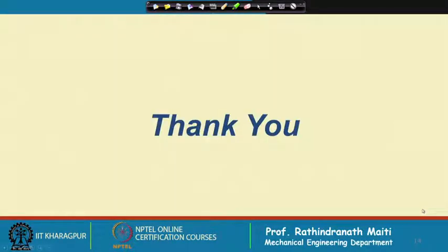Okay. Also the gear data we have provided here, and this is the end of the detailed drawing. Thank you. And I would like to mention here that while you are making a detailed drawing, for each and every component you have to make a detailed drawing. Okay. So, I have shown only a sample of the one shaft with integral pinion. I think following that you can develop the detailed drawing of the input gear, and following the first stage gear drawing you can easily develop the second stage gear.